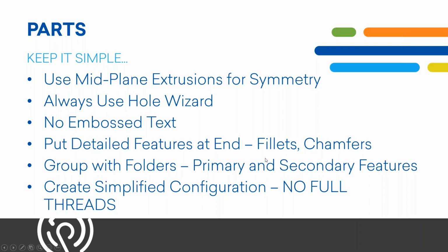So when we were talking about fillets and chamfers, those we would like to have at the end of our modeling tree, and we're going to show you that that's going to allow you to simplify your models later. First of all, they're complex features. So if you have features that are child features to them, if you make any kind of adjustments, usually you're going to break something. So you want those at the end anyways. Anytime something's broken, it takes longer for the computer to process it. So you want things to break as little as possible, let alone the frustration that you will avoid.